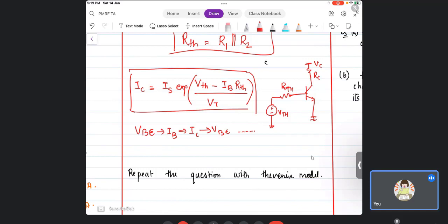The same process will continue here as well, but we will see how the variations will come. Therefore in the resistor divider model, with the proper choice of R1 and R2, as we had seen in the first method, you will automatically make base current negligible, and therefore the variation with respect to beta will be very low. But if you are not able to do that, then there is an exponential dependence that will lead to bigger variations.